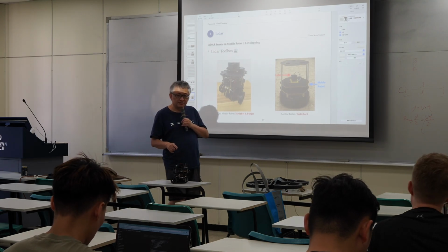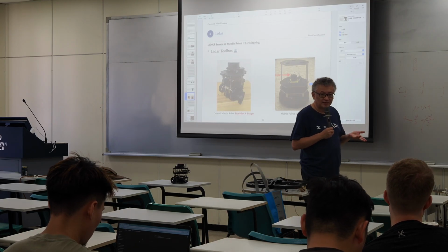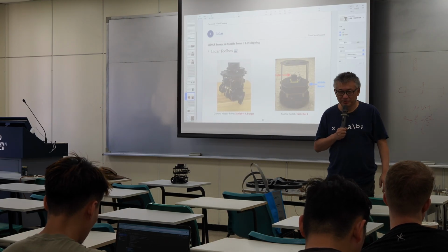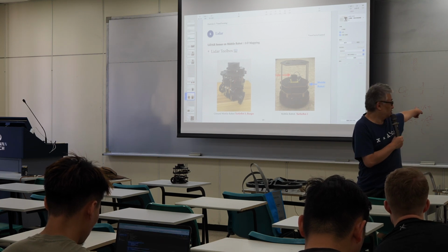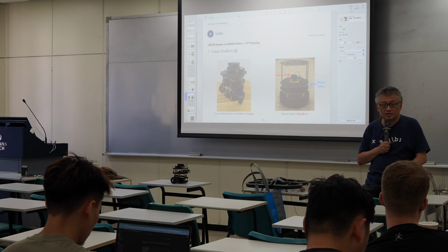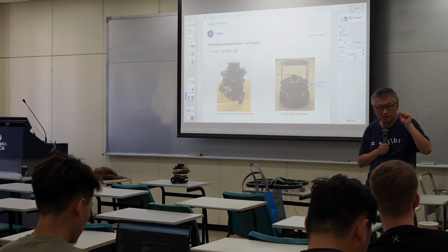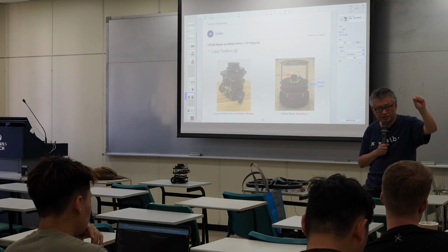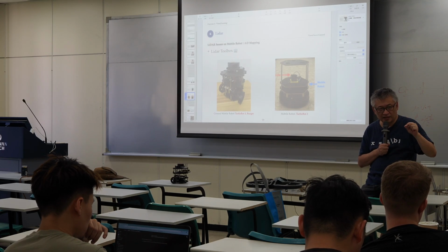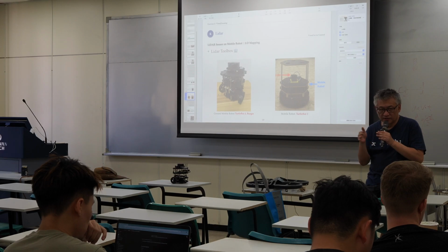Alright, so then next is LiDAR. This is LiDAR. Well, I think Jacob knows what LiDAR is. Tell me the operating principle. Basic principle is time of flight. It's using the same technique as time of flight. There is a light, infrared light, that goes out. So you measure the time it takes to come back, divide by 2, and that will be the range. So basically, it's one laser rotating for 3D.